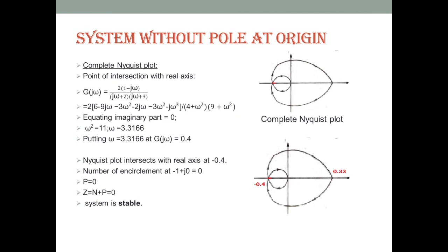That means the contour in the Q(s) plane is identical to the contour in the G(s)H(s) plane if we shift the origin from 0 to the -1 plus j0 point, and hence the Nyquist plot is the mapping of the Nyquist contour C in the GH plane with the origin shifted from 0 to the -1 plus j0 point.